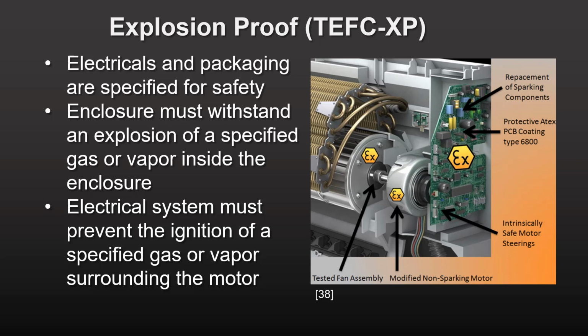The enclosure must withstand an explosion of a specified gas or vapor inside it. Test labs literally explode a gas inside the enclosure and watch what happens, safely from afar that is. Some of the technicians in these labs rather enjoy the pyrotechnics on display. These are the guys who spent their childhood playing with matches and fireworks rather than playing video games.